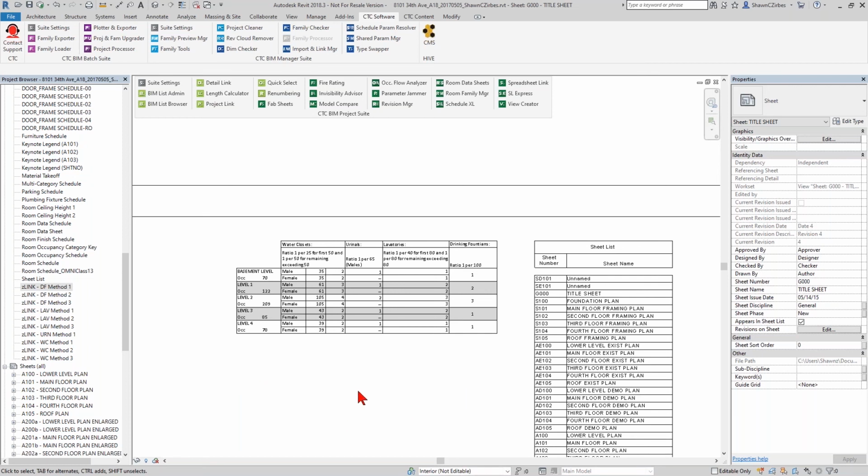And the next time there's design changes from the architecture team, I simply rerun Spreadsheet Link and apply my room properties back, and then just refresh my schedule Excel list, and I print, and I'm done. That's 5 minutes for full occupancy calcs, full code compliancy calcs on a real project, 5 minutes or less, and I'm ready to print. As opposed to the manual process of validating visually for 2 hours and then re-updating those links and then printing. This saves you 2 hours every time you want to print if you're doing calculations in this type of fashion. Can make it real easy.